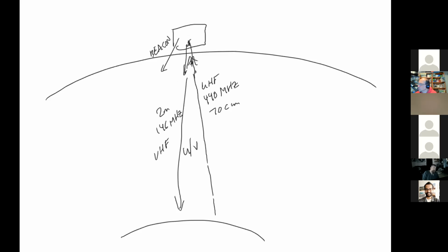Well, if you are transmitting on an uplink with too much power, your signal on the satellite downlink will be too loud and other people won't be able to get in and be heard. So you try to make your signal coming out about the same audio level as the beacon.